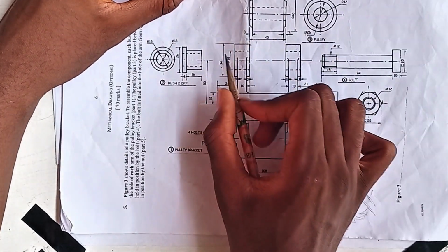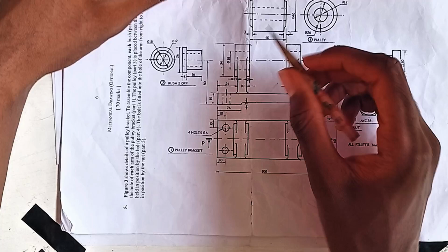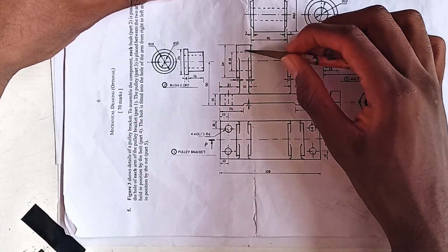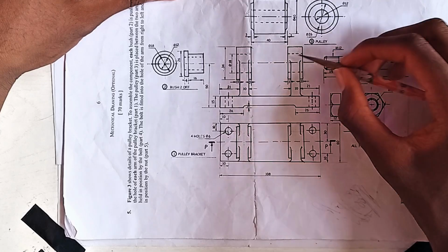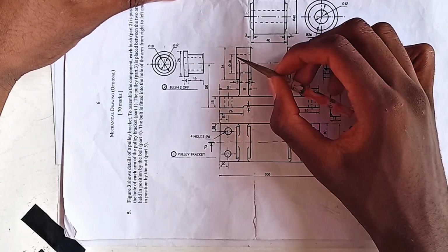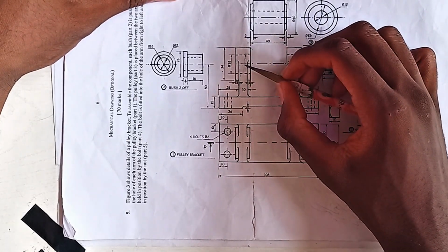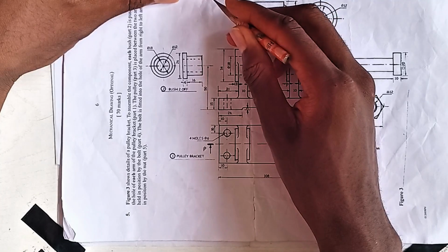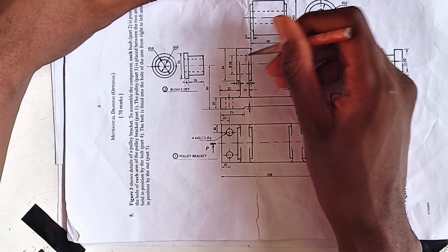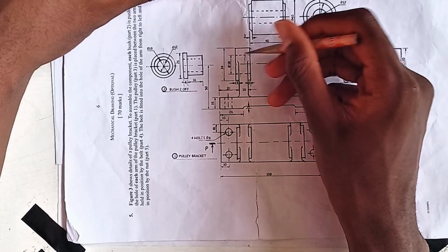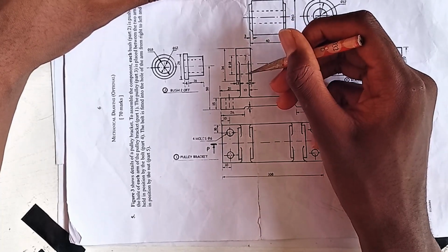So this bush has to enter into the hole. So where's the hole? As you can see, there's a hidden detail. This hidden detail line is being drawn at this part and these parts here. So that means this actually represents the hole, because remember, a hidden detail line shows that there's something inside the block that you can't see. So that's why the line is always drawn. So this line now shows that this is where the hole of the arm actually is.